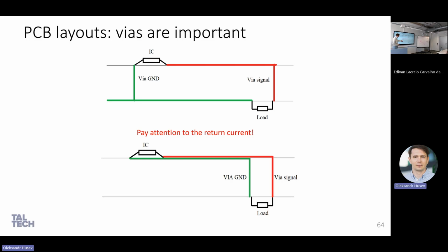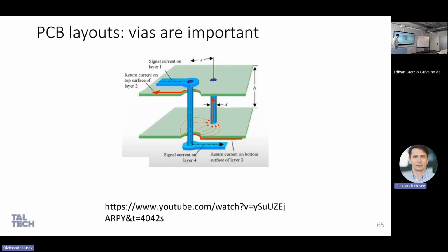Will you pay for this? Yes, because you usually pay for the number of vias, which adds extra cost. Also, if you have blind vias, it's terrible, your PCB will go like 10 times more expensive. I don't recommend it except for some specific cases. But usually, if you have the opportunity to put in a via, it doesn't matter in which place, the amount of vias is important.